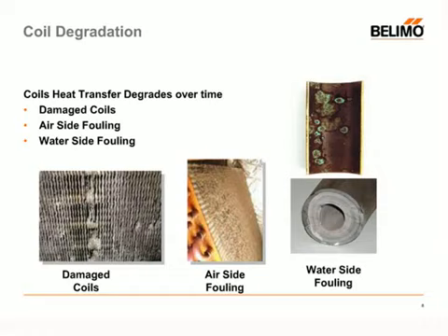Now we talk about airside fouling. If you see this picture here of the coil, we see a layer of dust over this coil. Coils typically have filters in front of them, not furnaces. Furnaces would not be good. So they have filters in front of them that are supposed to capture this dirt and debris, and those are supposed to be changed at specific intervals.